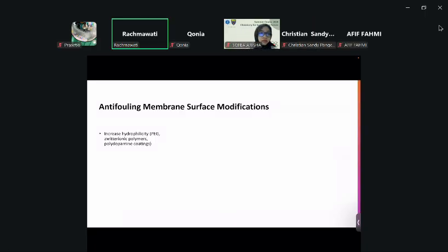Now you want to stop that. So for example, by increasing hydrophilicity, you introduce PEG, you introduce zwitterionic polymers, or you coat the polymer using polydopamine, and you also aim to reduce the roughness, so you are aiming for a smoother active layer of the membrane.